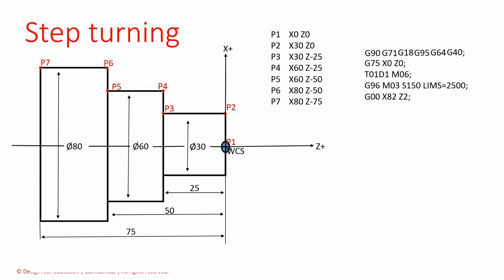Why are we activating the G00 code here? Because that area is a non-cutting area. Next, activate the coolant. That code is M08. Up to now, we are just activating the commands. Next, the shaper. Now, the tool is in a safe position.